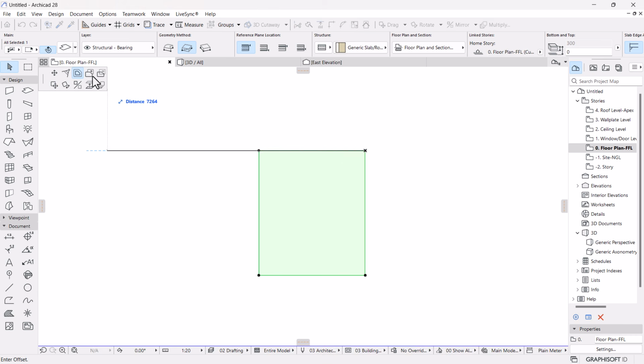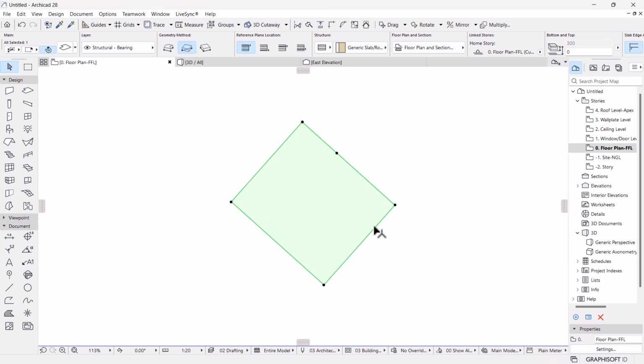And then we have where we want to add another polygon, maybe we want to introduce another kink of a slab like that, or we can subtract this like that. If you click on it, you can also elevate, you can multiply, you can rotate like we did with the wall.